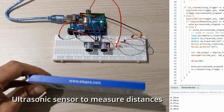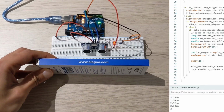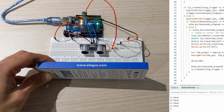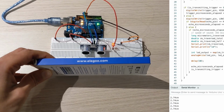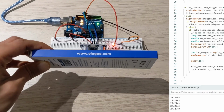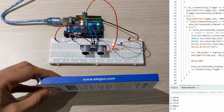This is an ultrasonic sensor that can be used to measure distances, and it's using a custom algorithm built from scratch because I wondered why an external module was required in the provided example code, since you just need to take into account the speed of sound and the time it takes for an emitted ultrasonic pulse to be received back by the sensor. I've validated the measurements using a real-life ruler, and they're actually accurate. No external code modules required.